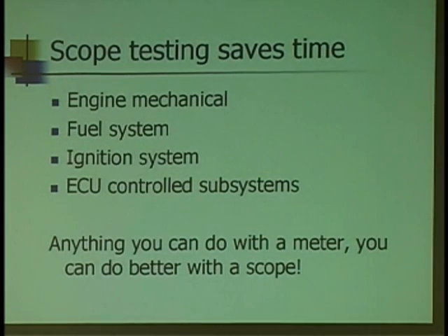I think scope testing saves me a lot of time, and I can use it on nearly every system on the car and then some. Anything that you can measure with your multimeter, you can measure with your scope. And there's a lot of things you can measure with your scope that you can't touch with your multimeter. Okay. I would say this to you: the only limits to your scope are your own personal imaginations.